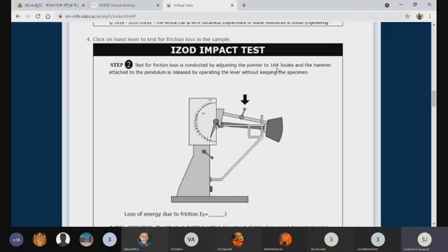As per the standard ASTM standards, we can apply exactly 164 only. But residual stresses are already present in the machine, around 4 joules. If you apply 164, we will consider only 164 in the calculation. But once we apply this 164, there will also be 4 joules present as residual stresses. Now how much is it? 164 plus 4.